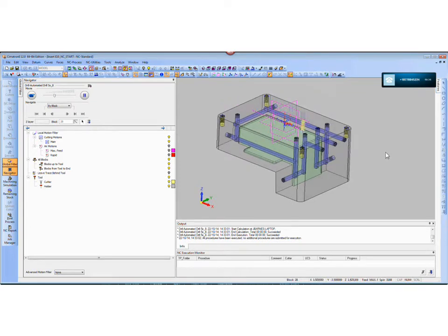The one thing that Cimatron does in this situation, this 422 diameter drill, as you know, is actually 0.4219. In fact, I think it's 0.42187. If you import this geometry through STEP or IGES, it might be 421 or 422 or 421 and 9/10.